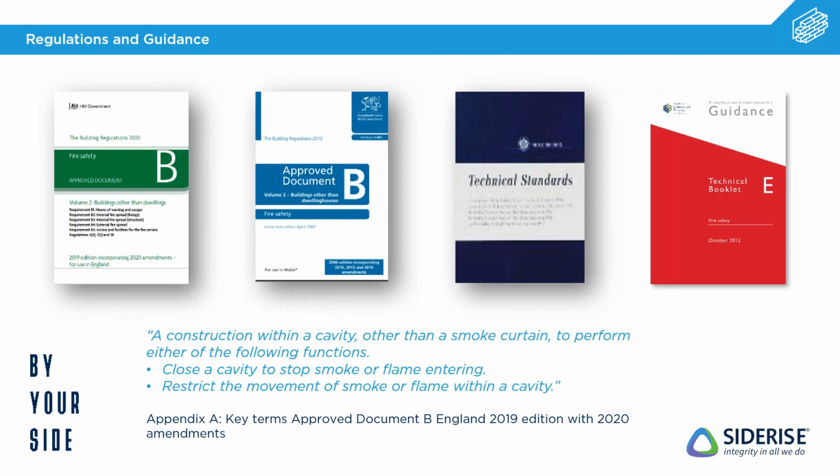So getting a little bit more into detail on some of this guidance or requirements that are out there. As I said, first of all, we have the national documents, which differ depending on which country within the UK we're looking at. So for England and Wales, we have Approved Document B, slightly different variations for the two. So you can see there the green version, which is England, and blue for Wales. You then have the Technical Standards, Volume 2 for Scotland, and Technical Booklet E for Northern Ireland.